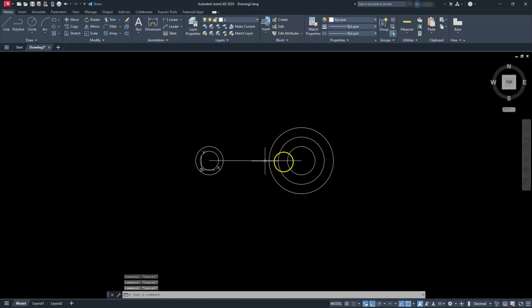Next, let's create another line, and it's the same distance as this line here. I've got 2 different options. I can copy this line from this endpoint to this one, so I'll do that first. And then I'm going to show you another command that we may not have used. I can select this grip with the space bar one time, and then click onto this endpoint. All that is just moving grips, and I'm just moving that object. It's the same distance, and there it is here.